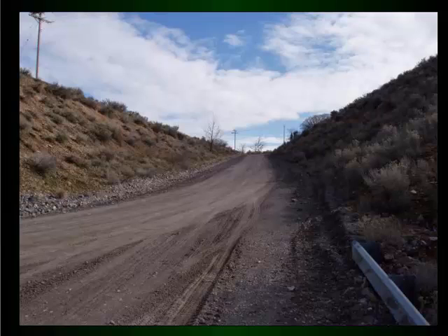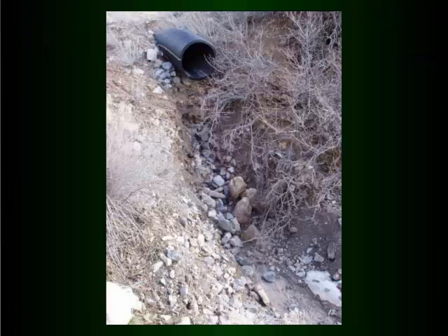On the way through, you'll see we head up this through cut. And obviously in a through cut, you have no place to kick water off. Once you get from the top of the cut to the bottom, you just have to deal with it. And one thing is you can put open rock. You can armor, say, the ditch line with rock so that it can't cut, or you can actually put some drain rock in it and put a drain pipe underneath it.